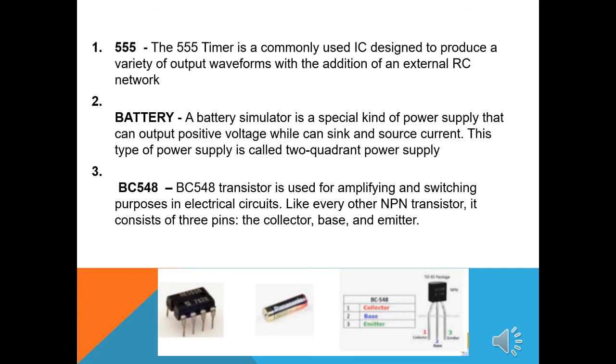Then the second component is the battery. A battery simulator is a special kind of power supply that can output positive voltage while it can sink and source current. This type of power supply is called a two-quadrant power supply.